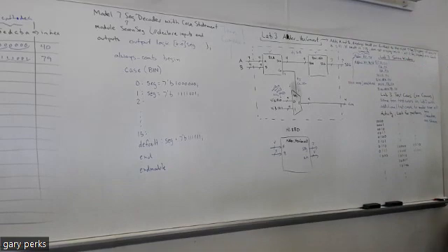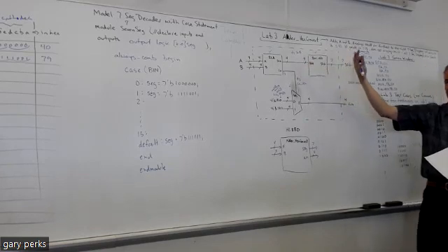Now, as a hint, I would write out 4-bit numbers from 0 all the way to 31, right? This would represent your possible outputs of your RCA. Because here the carry out is 0, that's why you always see 4 bits. But then once it gets to 16, your carry out would be 1, and it would just go from 16 to 31. So I would write out all your possible outputs of your RCA, the sum and the carry out together.